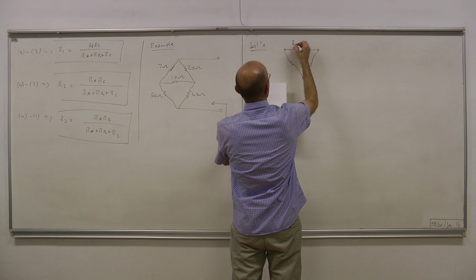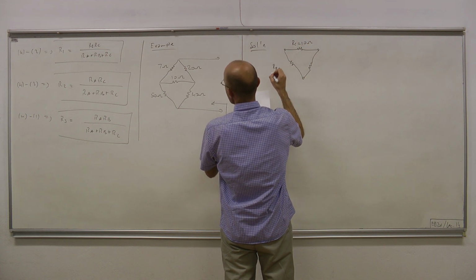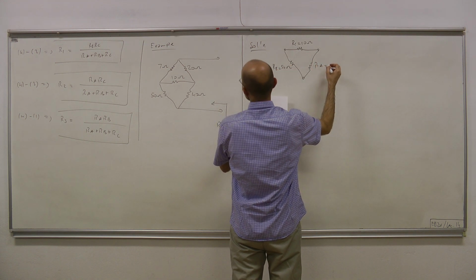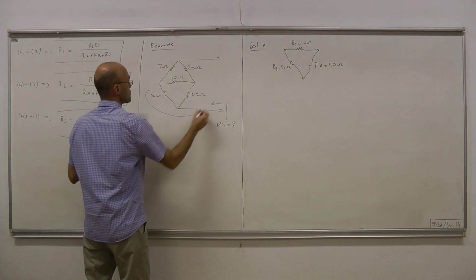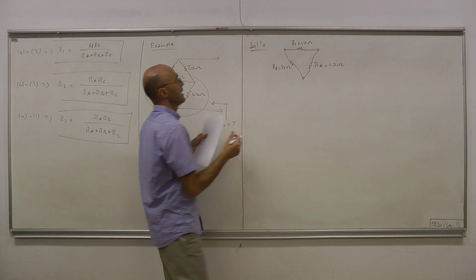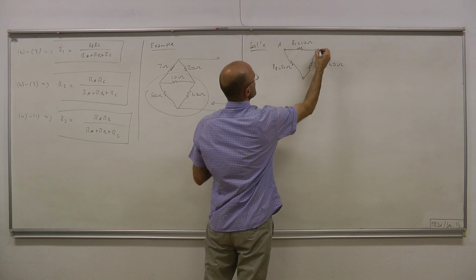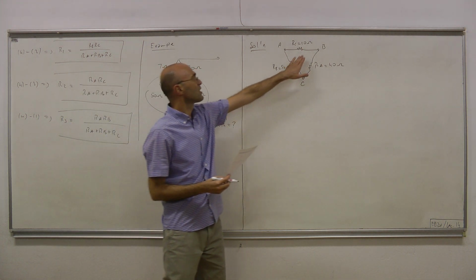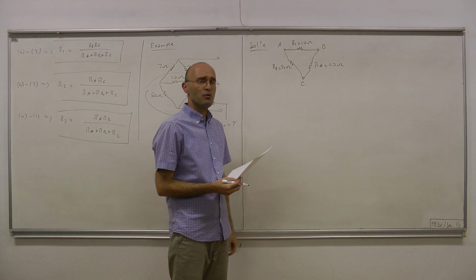We have RC equals 10 ohms, RB equals 50 ohms, and RA equals 40 ohms. So we're concentrating on the delta connection that appears here, and we're labeling the nodes as follows. This is node A, this is node B, and this is node C. We know that this can be represented by a Y-connected set of 3 resistors.